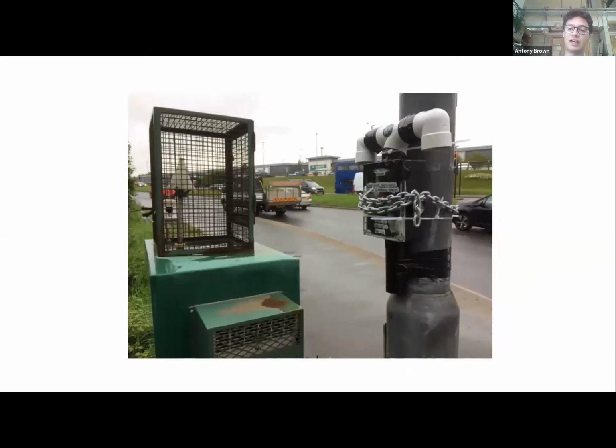So we had data from these initial tests showing that the sensors worked, but we didn't know how well they represented actual pollution levels on the road and on the estuary. So an important next step was to run co-locations with our sensor against Cornwall Council reference stations. We did this in Truro. We attached one of our sensors to a lamppost about 1 meter from a reference monitor and left it there for 36 hours.